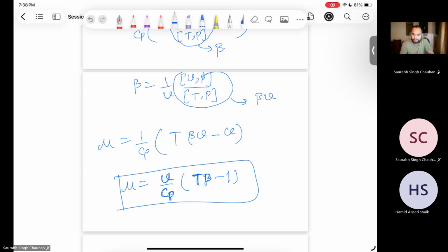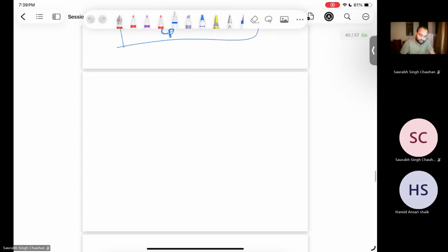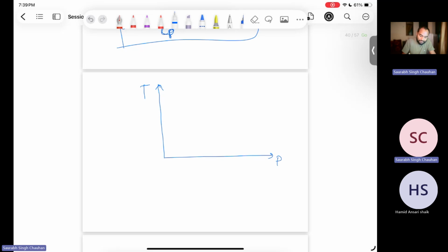And what is the Joule-Thomson coefficient? Where is it used? It's used along the lines and for the throttle valves. And where do we use throttling? In refrigeration we use it, right? Yes, sir. To reduce the pressure. Okay. So actually, on the T and P axes, we can make isenthalpic lines, because this is an isenthalpic process. So during throttling, pressure will be reduced.